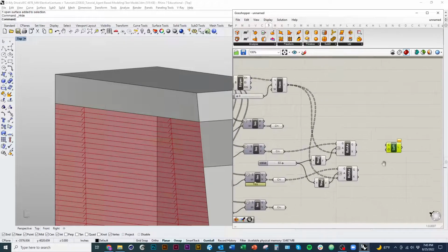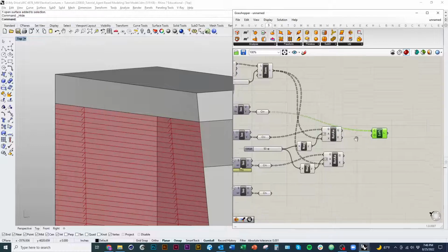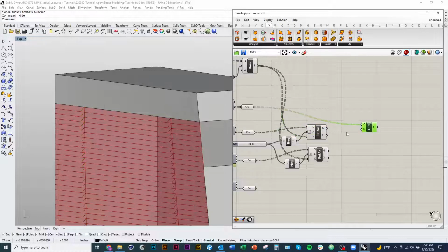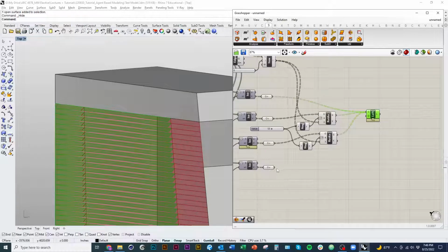Now in Grasshopper, you can plug multiple inputs into an item. So if I drag from my first curve there, and I want to plug this one in as well, I'm going to hold Shift, and you can see my little cursor giving me a green arrow. Now it's important the order in which you select curves when you loft stuff in Rhino.